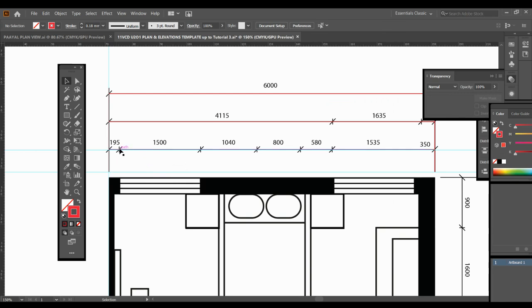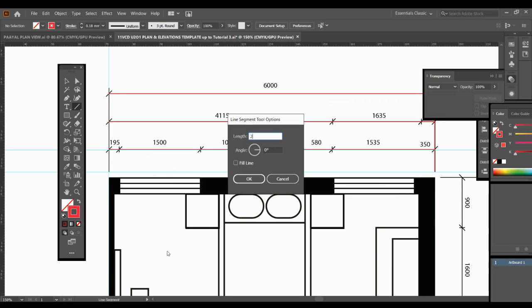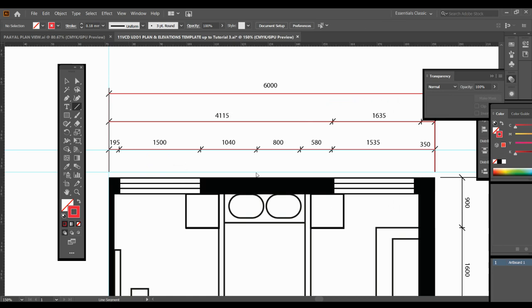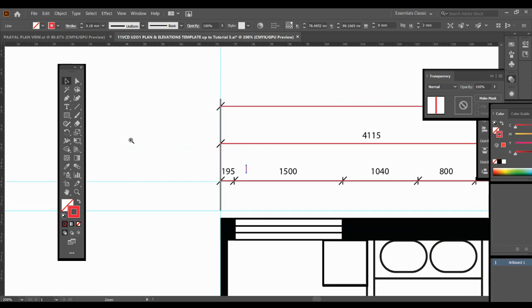So now we've got all of these lines here, which have to be vertical and they have to be 2 millimeters long. So the length is 2, the angle will be 90. Okay. And so we can just place those along our measurements on top of our traced image and center them on the line.